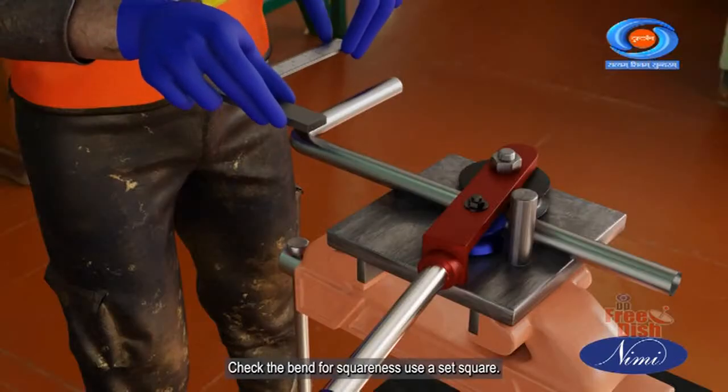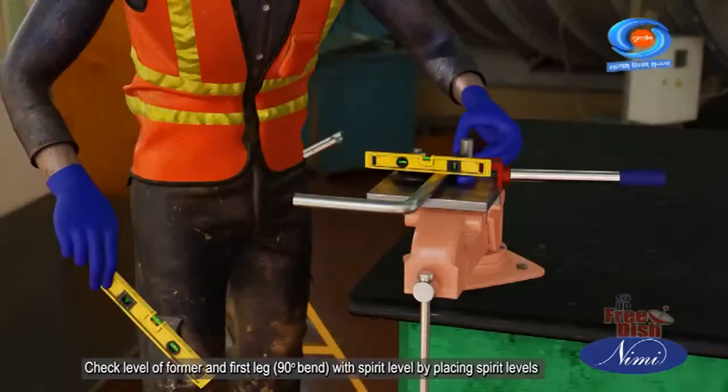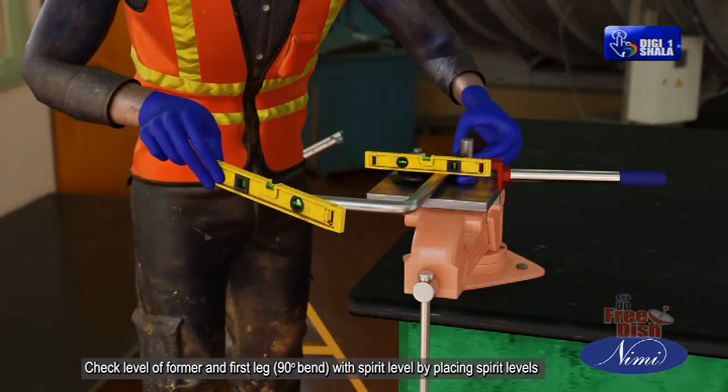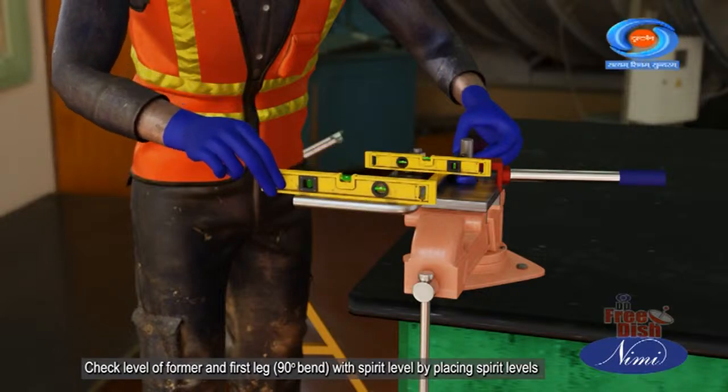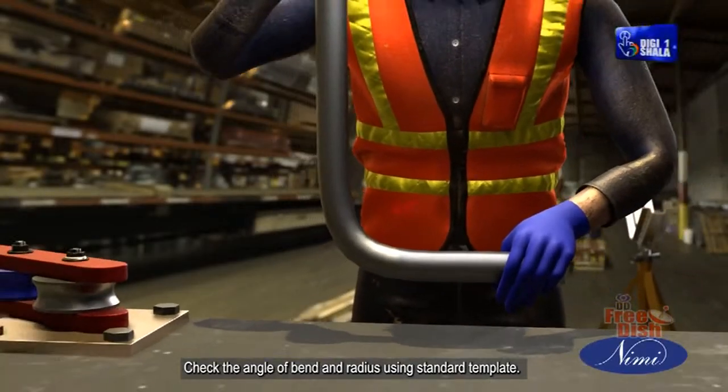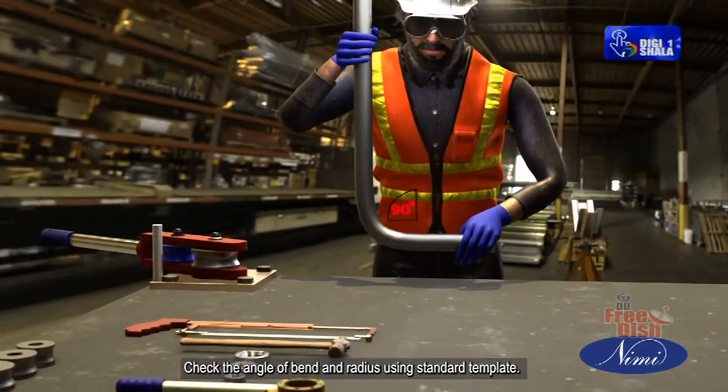Check the bend for squareness, use a set square. Check level of former and first leg 90-degree bend with a spirit level by placing spirit levels. Check the angle of bend and radius using a standard template.